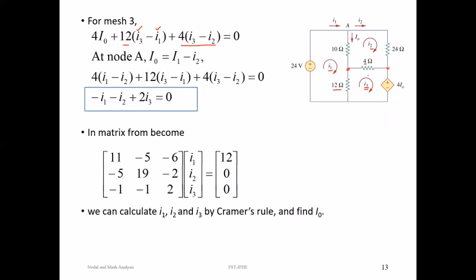Now, when you are flowing through this particular mesh, you are encountering what we should treat as a voltage source only. When you are flowing in a clockwise direction, you are touching plus, so we are using a plus. And what is the voltage value of this dependent voltage source? 4I naught. So we are writing 4I naught.